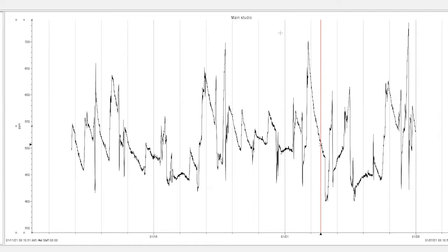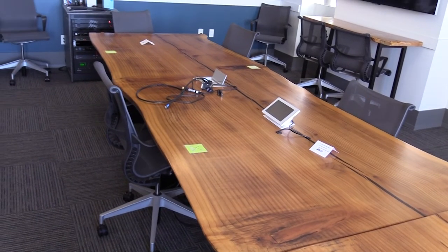For example, take an incremental approach, maybe adjust the outside air damper by about 10%, measure again, and see if you're within acceptable levels. If your building automation system or control system will allow you to adjust the outside air damper during those periods where you know you have an increase, during a specific class period for example, then that might be one strategy to ventilate more fresh air while still keeping your energy efficiency in check. It's also important to measure CO2 levels in multiple spaces in a building, especially shared workspaces, conference rooms, cafeterias, etc.